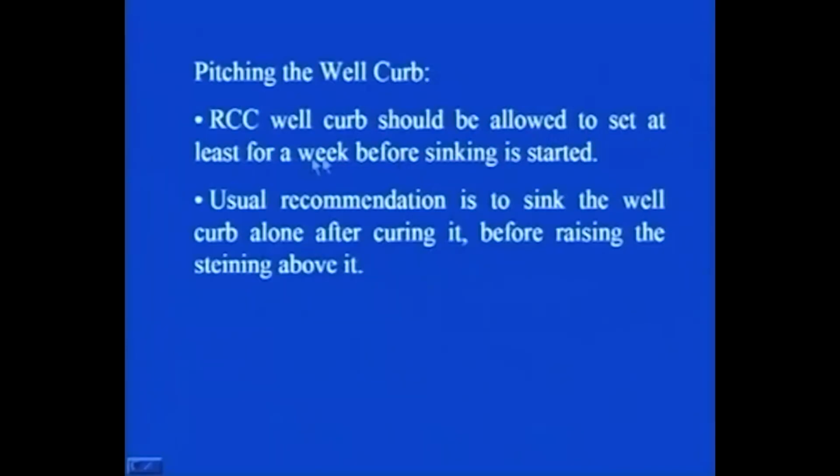Then the RCC well curb should be allowed to set at least for a week before sinking is started. So, 1 week time you have to give. The usual recommendation is to sink the well curb alone after curing it, before raising the steining above it. You know that the well curb is the lowermost part of the well foundation, and on top of that it is connected to the well steining.